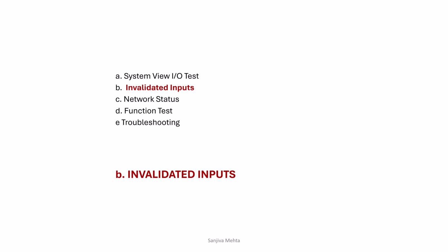Invalidated input. Inputs are invalidated. It has nothing to do with cutout, manual cutout or automatic cutout. You are invalidating input, the input to the controllers, input coming from various sensors. If you feel that input is faulty, you are invalidating that input. Is that clear?